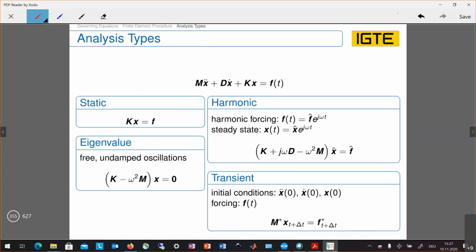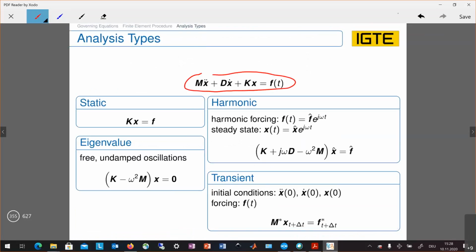Okay, so collecting all this together, we have our semi-discrete Galerkin formulation, as it is also called, because we are still continuous in time. We have the second time derivative with the two dots written here. So these are the accelerations, the unknown velocities, and the unknown mechanical displacement.